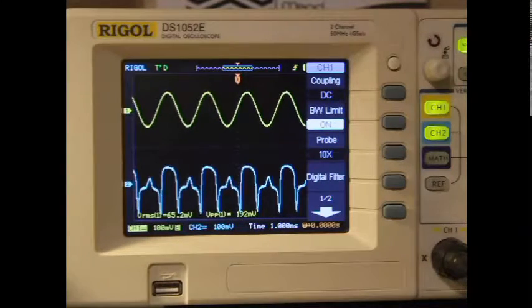Now, what do we have here? This yellow trace you see at the top is an input signal. This is a sine wave that is oscillating at 440 Hertz, which is the frequency of an A note, concert A. That is the top trace. The bottom trace is the output of the Octomotron Fuzz. You can see it looks pretty different from the input.